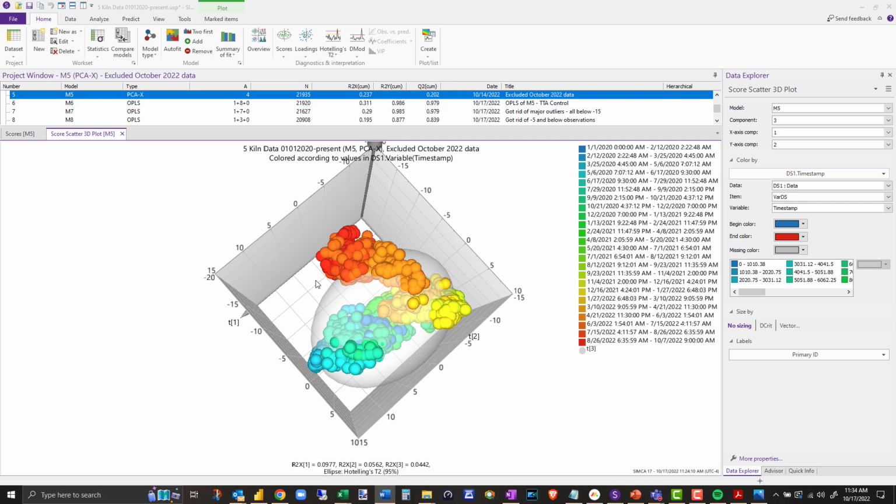It was a big pharma, and I was asked, okay, well, we have a process. How much data do I need to pull out? We sample like every 3 seconds. Do I need to pull out every 3-second data? And I'm like, well, how long is your overall process? They're like, oh, it takes like 14 days. So I said, in all seriousness, do you really think it's necessary to have 3-second data for a 14-day process? How fast is the fastest transient you think you're going to need to capture?